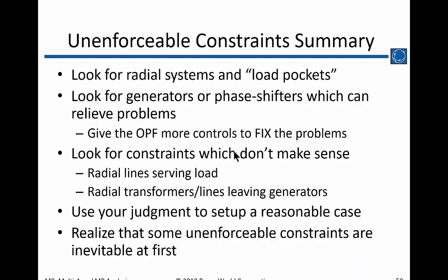Just kind of the summary: things that might not make sense might be due to high reactive power flows. They might be due to phase shifters that are on settings that don't quite match the load or don't quite match the ratings of lines that they're in series with. You just might need to use some judgment to either ignore or relax constraints, or just remove things that look kind of funny.